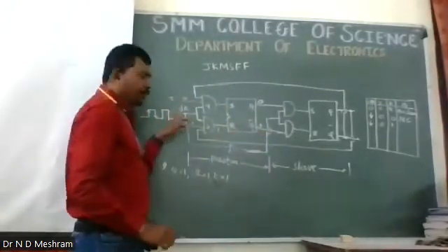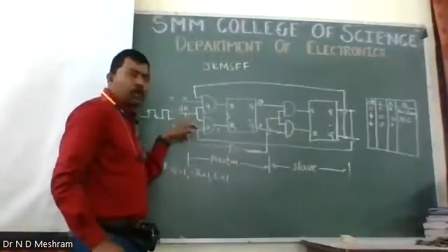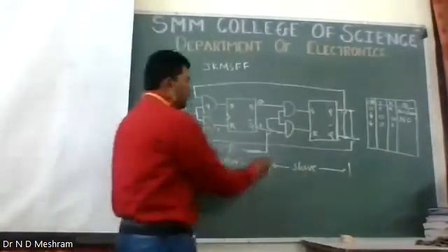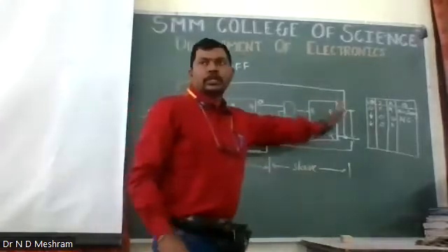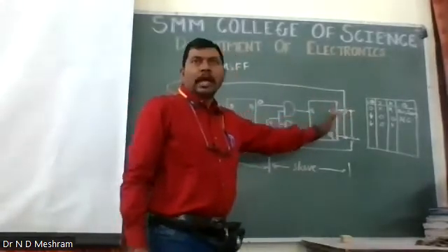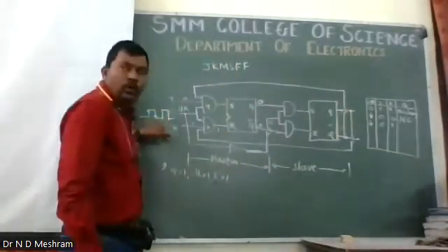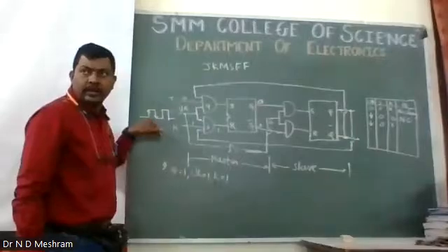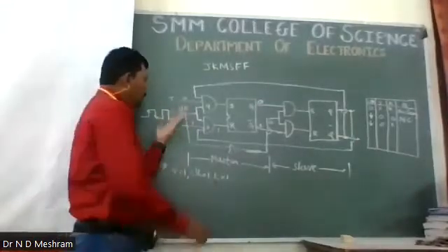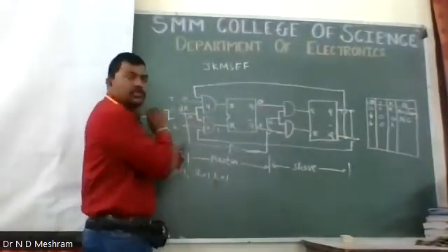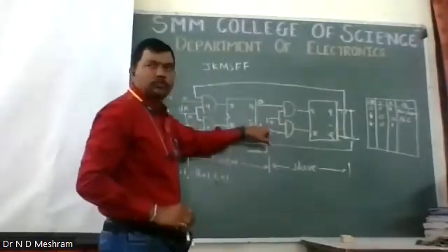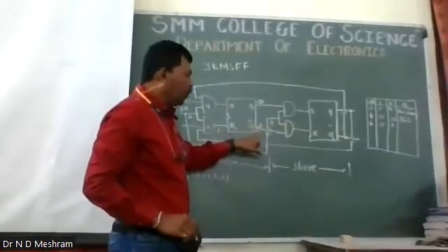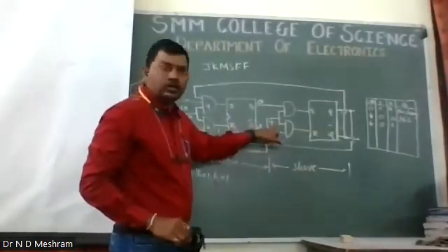Now if you look at the clock, this is 1, this is high, so automatically this will become 0. So nothing is going to be inputted inside the second flip-flop. As soon as this output goes low, the negative edge comes, this clock will become 0 and this will become 1. As soon as it becomes 1, again Q bar is 1 and clock is 1.